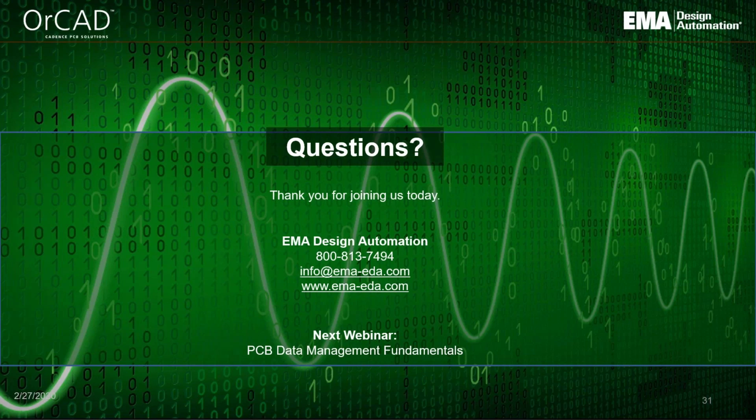Yes, it does. In the demo you saw, I went to the stack-up editor and showed you the stack-up relative to the layout. That stack-up information comes into the Sigrity tools via the board database. So from Allegro, it would be in the .brd file, the board file. That's where it starts.